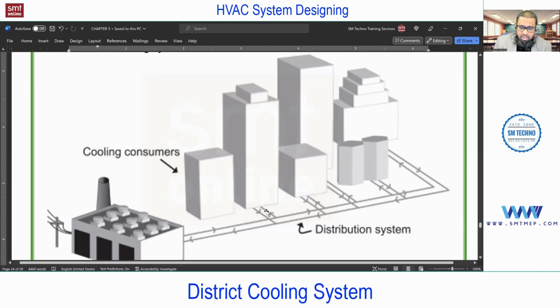Similarly, when the chilled water is entering the building, first it will connect to the BTU meter, and as per the requirement of the building, for example, it's a multi-tenant building, or assume that this building is a residential building with n number of flats, and the owner of each flat is different. Multi-owner buildings means multi-flat owner buildings. So everyone is going to pay the bill according to the usage. So in that case, for each flat, you'll find one BTU meter.